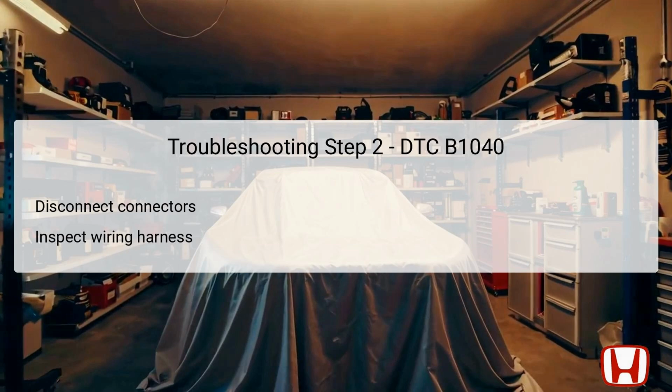Confirming the condition of these connections is critical, as they play a vital role in maintaining functional communication between the BCM and the wiper control unit. After ensuring that connections are secure and free of damage, the next step involves inspecting the +B wiper circuit.